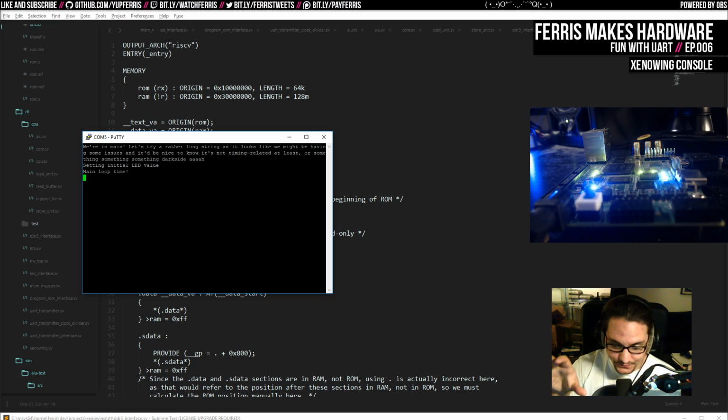Hey, Escatas. So what I want to do is, so we have this UART transmitter. What I want to do is first just do a loop back kind of thing, where if we start sending data on the UART, what I want the thing on the system to do is hold the CPU in reset and just route everything back to the transmitter.